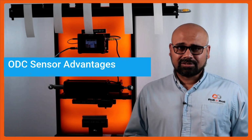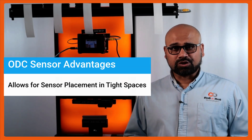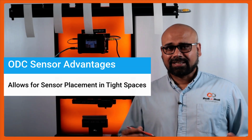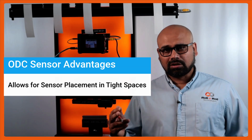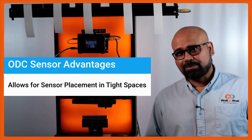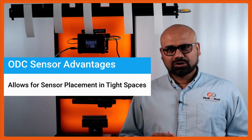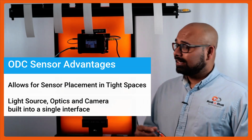Again, to reiterate some of the advantages of the ODC sensor, it's a one-sided sensor technology. So it allows us to install the sensor in tight installation spaces, whereas a camera-based traditional machine vision system might need a longer field of view and working distance, which creates issues if you want to add a width measurement system to an existing machine. The other advantage is that the light source, the optics, and the camera, everything is built into a single interface, like what we have here.